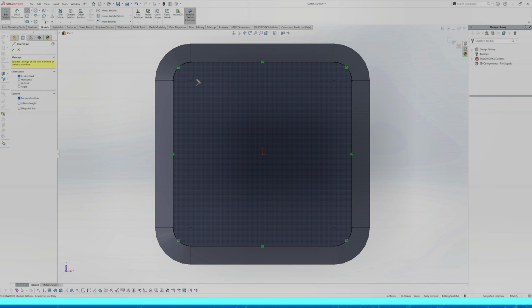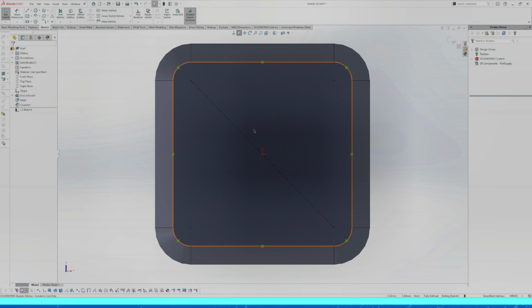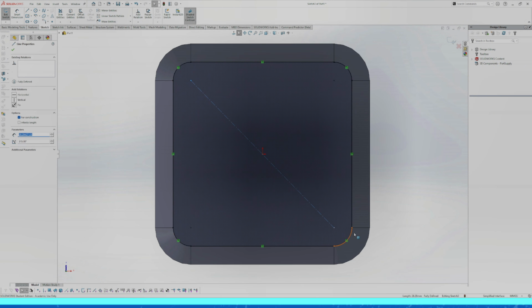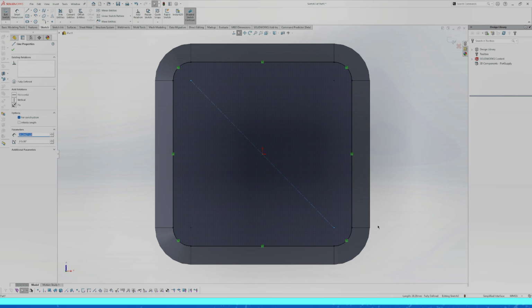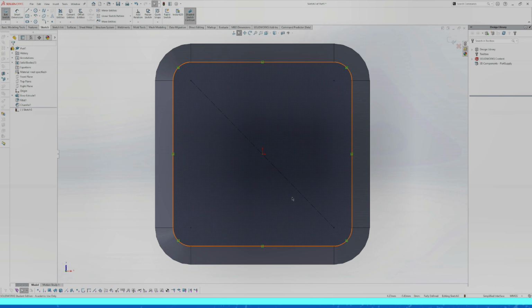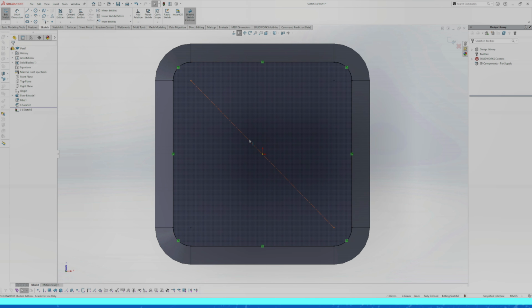So with that in mind, I can click right here, go all the way down here, and if I hit escape to deselect the tool, that is a universal button, you'll notice this is a different line type. This line type just indicates in SolidWorks that it is not something that has geometry. No matter what the shape is, this has no geometry that you can pull into 3D.